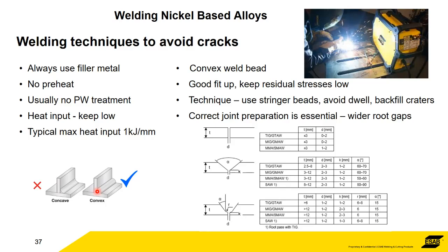It's much better to use multiple passes of small diameter wires rather than one big pass of a large diameter wire. Use stringer beads. Avoid dwell and backfill your craters. So if there is a crater, then fill it up. You need the material in there to hold it together.